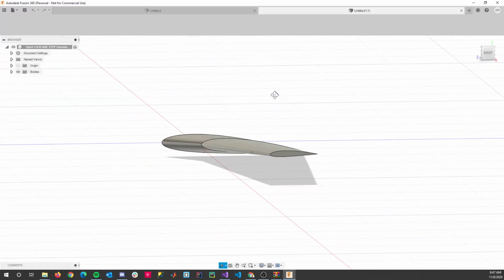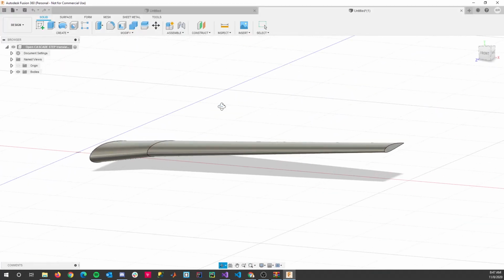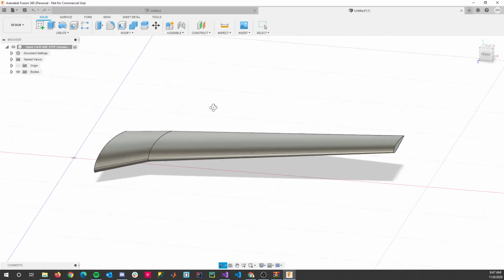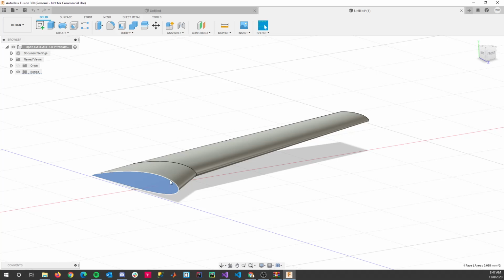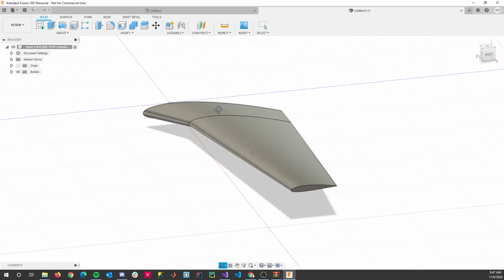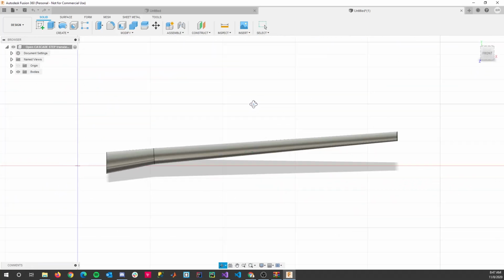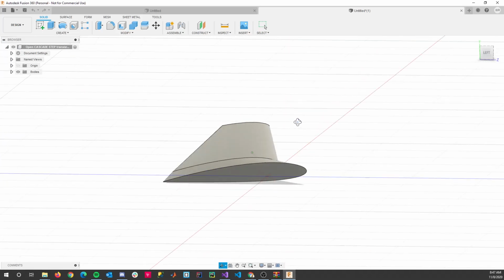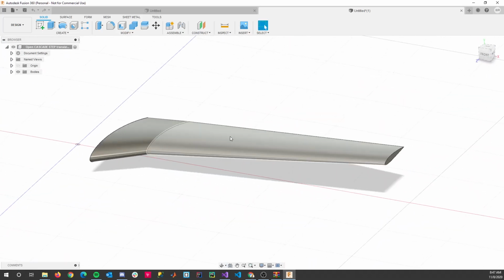And here you can see the 3D wing created, and so you can use this for CFD, or you can make it a shell and use it to represent the fiberglass, carbon fiber, or balsa wood covering that you use for your wing. And then you can actually import each of those CSV files for the ribs into your CAD application, and create a rib in there, and you can put this assembly all together.